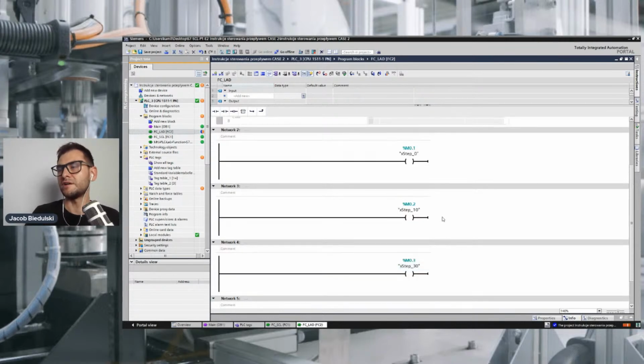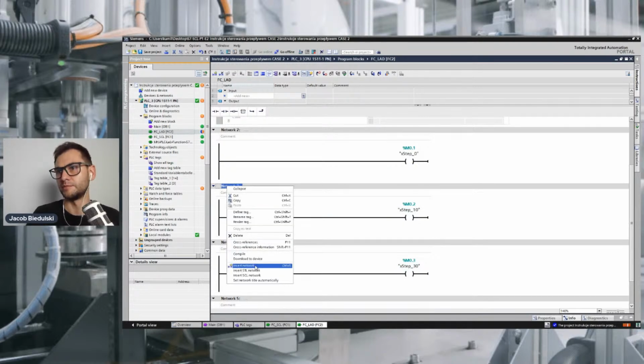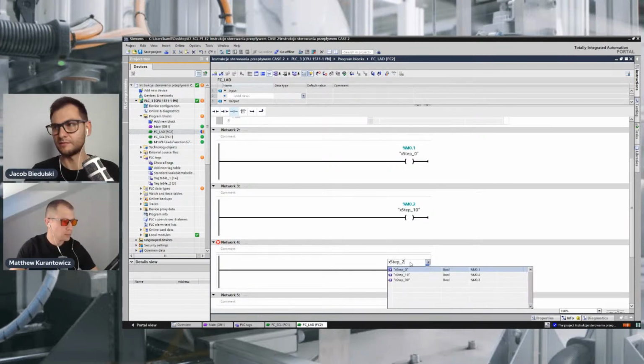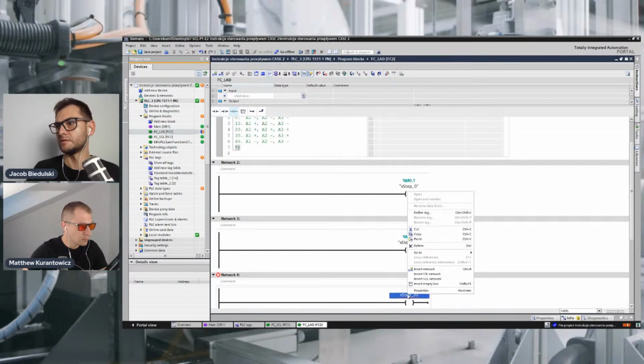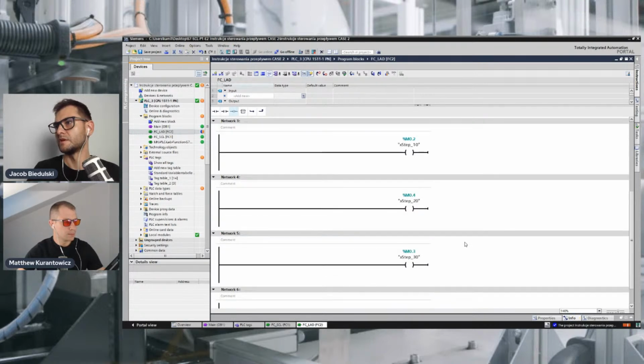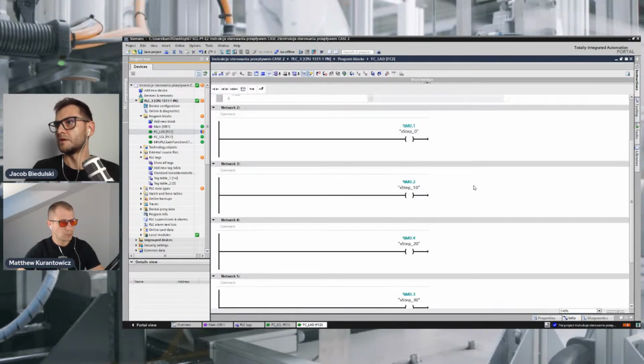You may wonder why I declare steps with an interval of 10. It's step number 0, 10, 30, maybe 20 will be also useful. In automation and robotics, we usually declare steps with an interval of 10. Why do we do it this way?